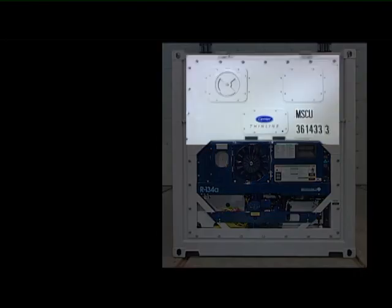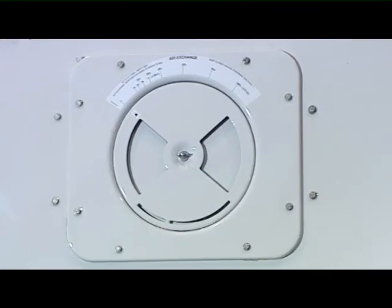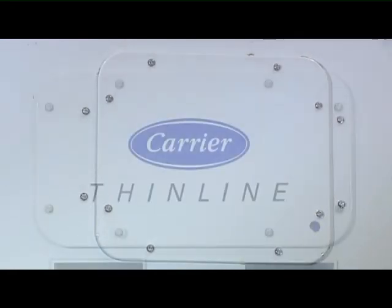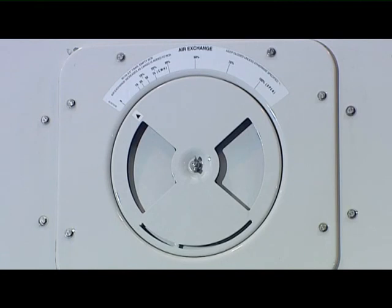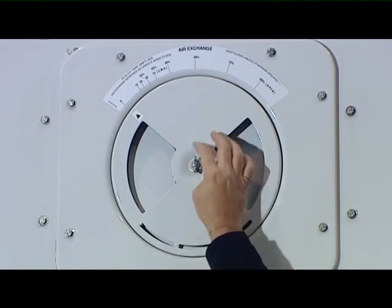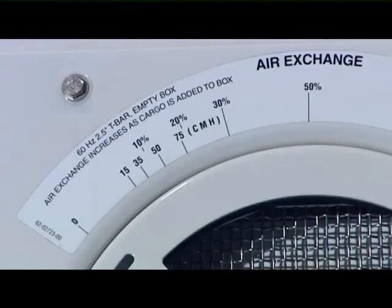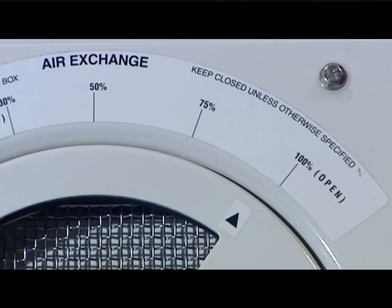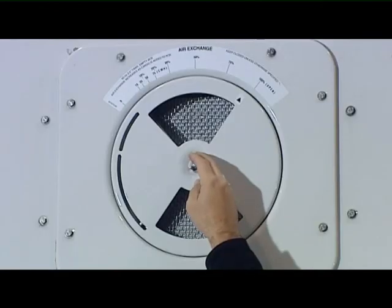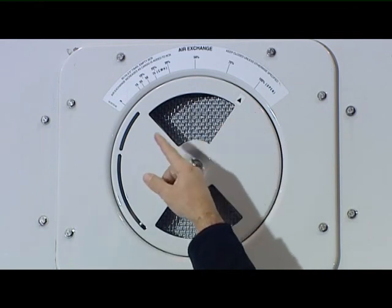Evaporator section. The evaporator section includes access panels, motors, heaters and TXV access panel, fresh air vents. The purpose of the fresh air vent is to provide ventilation for commodities that require fresh air circulation. The vent must be closed when transporting frozen cargoes. To adjust the percentage of airflow, loosen the nut and rotate the disc until the desired percentage of airflow meets the arrow. Refasten the nut.